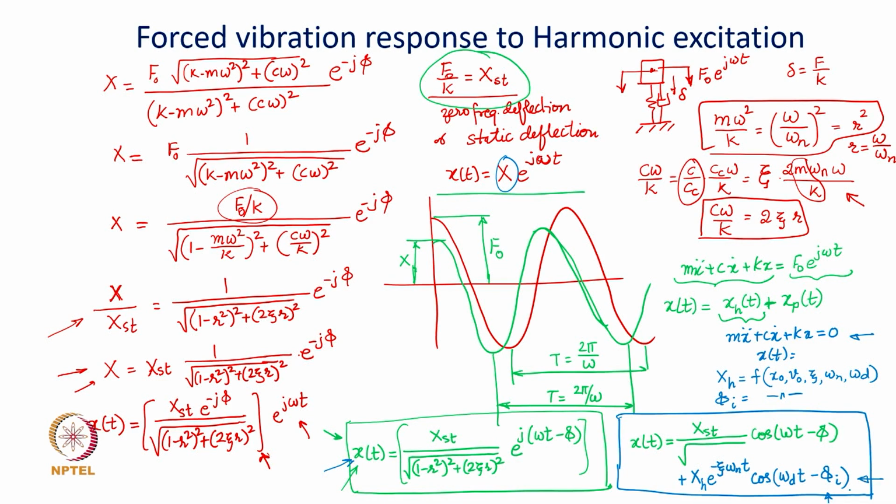Most of the times when the response to a steady state excitation force is required, we focus mainly on the first part of the solution, that is due to the steady state forcing function on the right hand side, and usually this part has relatively less relevance, or in fact is ignored altogether in assessing the forced vibration response.